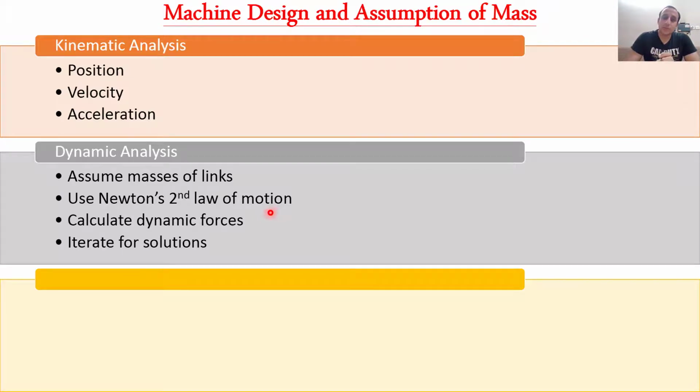Okay, so if the deflection is out of the limit, or it's affecting the actual working of the machine, and we are not getting the motion, the forces, or the direction of forces which we want, then we need to limit those forces, because if the dynamic force is less, the deflections will also reduce. Okay, so how can we reduce these forces?